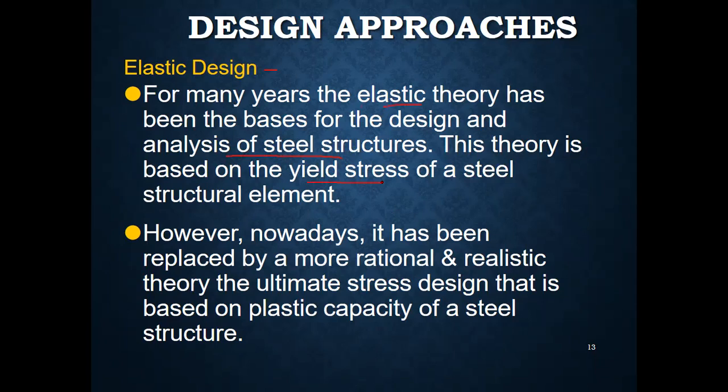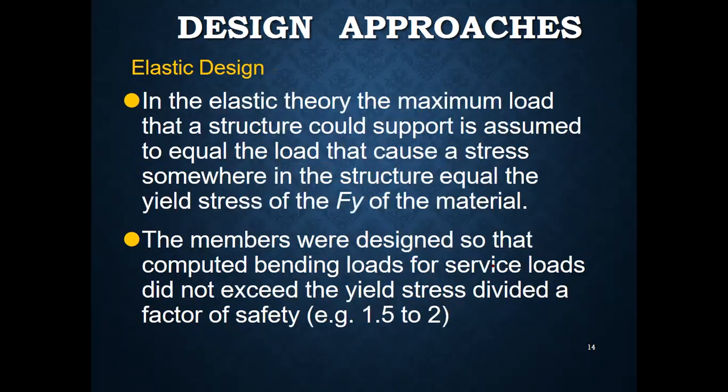But nowadays, this theory is replaced with another theory called the ultimate strength design theory, or the load and resistance factor design theory. This new theory is based on the plastic capacity of steel structures, and it proves to be a more rational and more realistic theory as compared to the elastic design theory.